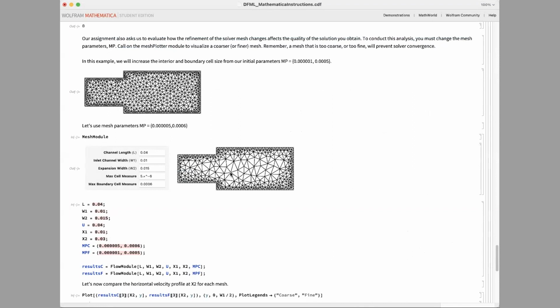Like you can guess for me, and maybe it'll have enough information to do it, maybe it won't. But depending on the type of mesh that you specify, you might be dealing with triangles. You might tell it you want squares or any type of quadrilateral element, or perhaps more. I haven't had the need to even venture beyond this triangular mesh because Mathematica does such a good job without even having to refine it. And you can specify if you want multiple points between your intersections.